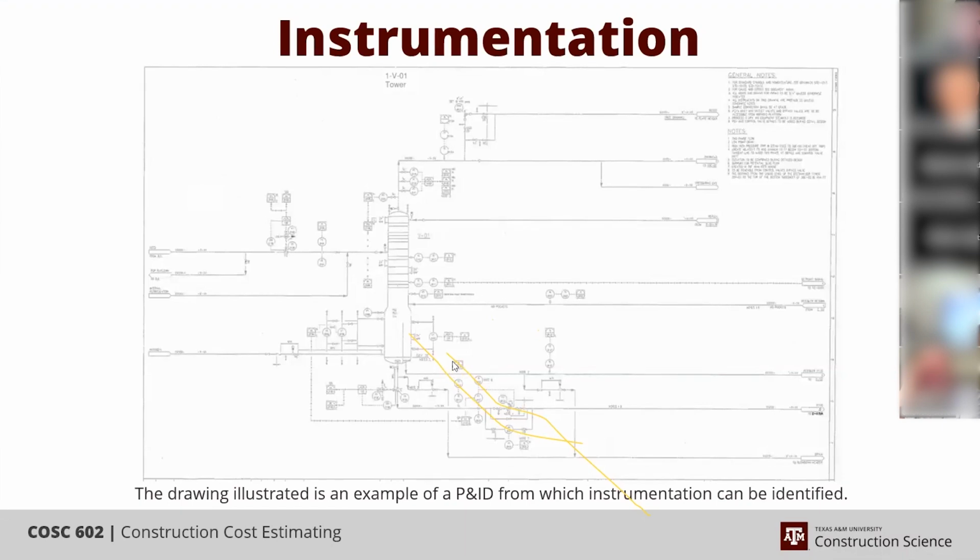Some of them are hard to memorize because they're actually indicators, or they may just be an alarm. They may just be a light on a panel. So if it's a circle with a square around it, it's in a panel somewhere. Actually, at this moment I'm blanking. If it's a dashed line, I believe it's a local panel, and if it's a solid line, it's back at the control room, or I may have that reversed. That's right.